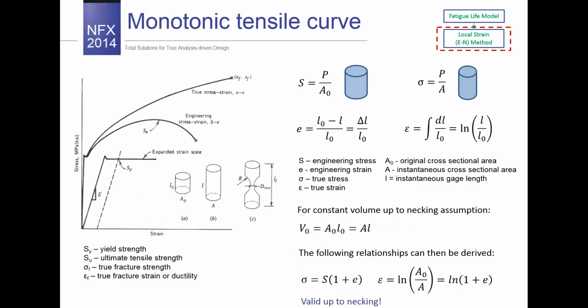At this moment, let's refresh some knowledge about monotonic and cyclic loading. Starting with the first one, this is quite important because the main topic for today is to perform a numerical fatigue test, in nCode, so a strain control simulation. Before that, let's talk about monotonic and cyclic curves. Monotonic behavior is obtained from a tension test, where a specimen with circular or rectangular cross-section within a uniform gauge length is subjected to a monotonically increasing tensile force until it fractures. This is the main definition.